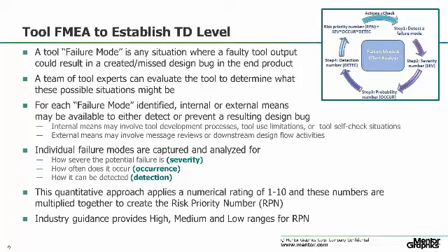So a failure mode is any situation where a tool output can result in either creation or a missed design bug in the end product. A team of tool experts, so people who fully understand how the software works, evaluate the tool to determine what these possible failure modes might be, and then for each failure mode identify either internal or external means to detect or prevent the software failure introducing or failing to detect a design bug.